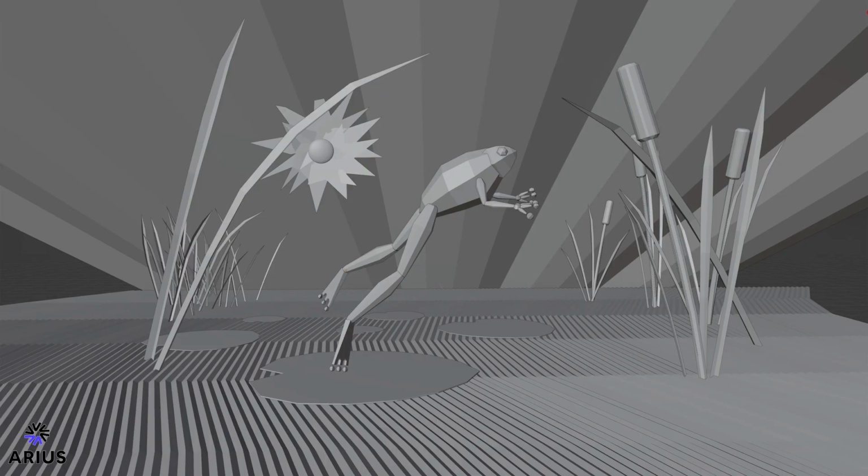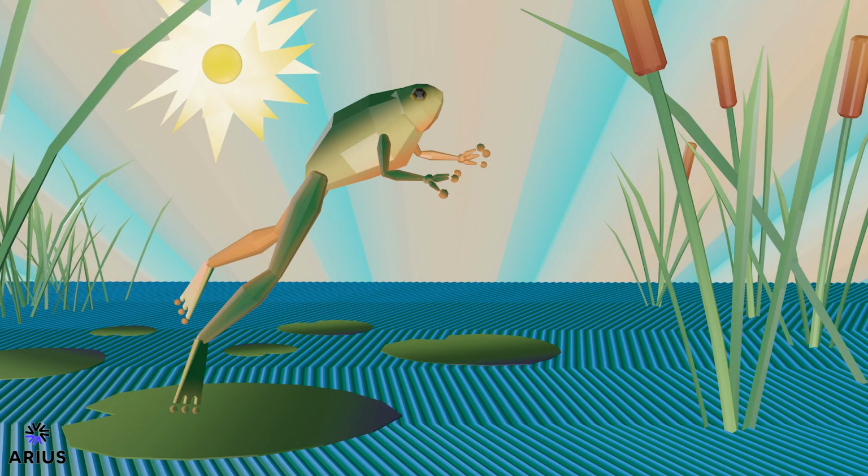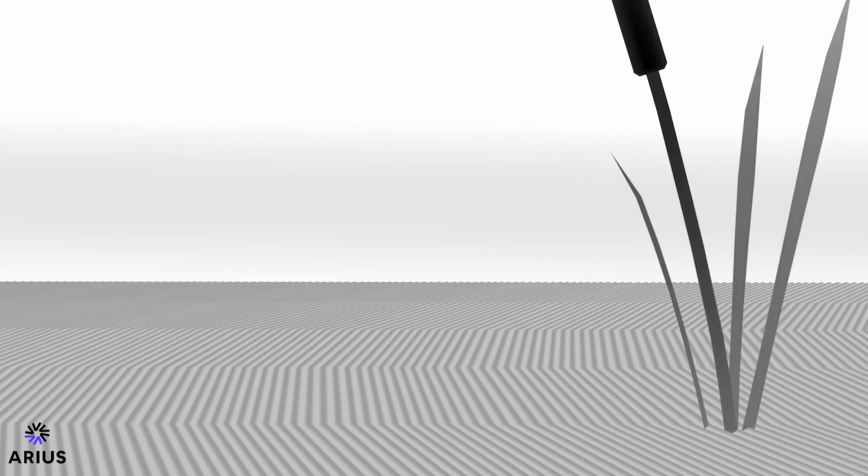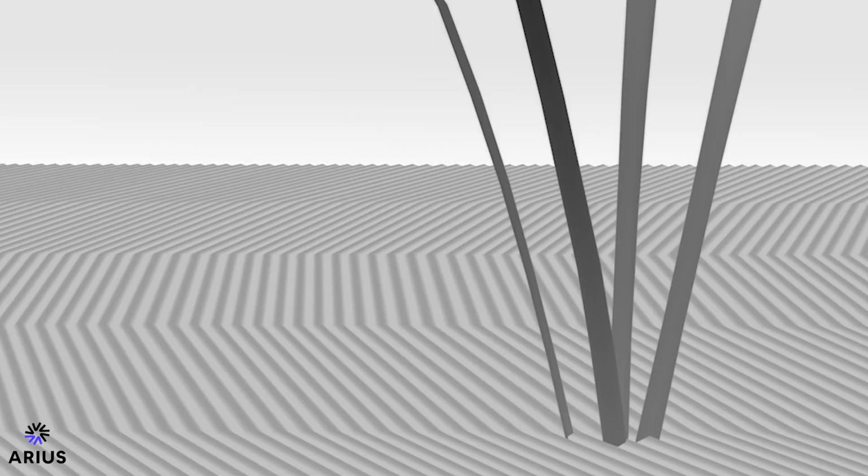To start with, render out a 16-bit TIFF color image. In Photoshop, convert it to grayscale and consider the tones and what they will give you in elevation at this point. If possible, render out each element of your image separately, if it needs to be elevated from the surrounding. The goal here is to have, for example, the water ripples as a complete layer, so there are no gaps under the foreground reed elements. Later, when softening the edges of the reeds on the layer above, we need to have wave pixels underneath the reed edge to blend to.